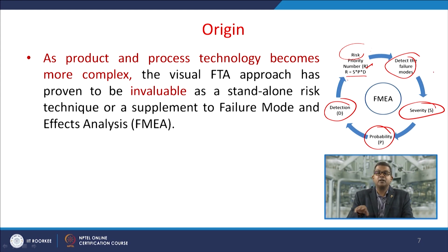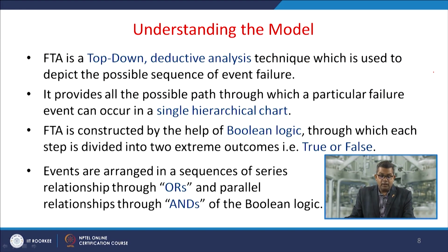So this is termed as the failure mode and effect analysis. Now let us have an understanding of the model that the fault tree analysis is a top-down deductive analysis technique which is used to depict the possible consequence or the possible sequence of any event failure. So it provides all the possible paths through which a particular failure event can occur in a single hierarchical chart.